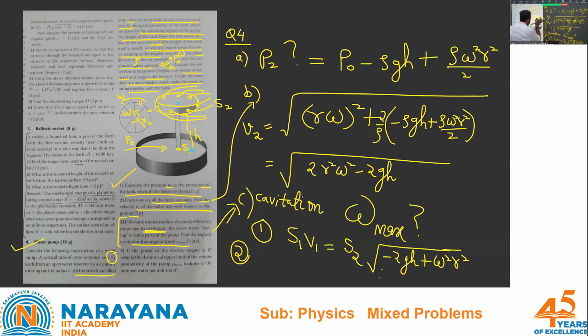to the center point where liquid is just coming up with V1, and this is all pipe where the velocity is V1. Let's apply it in between. So at this point, only pressure energy is there, that is P naught. That is the reference. So when I write those terms at the midpoint, I'm writing pressure there as PM. That is not exposed.